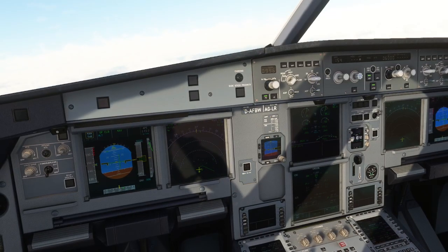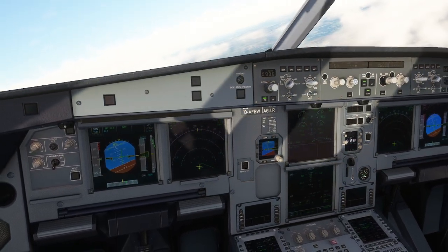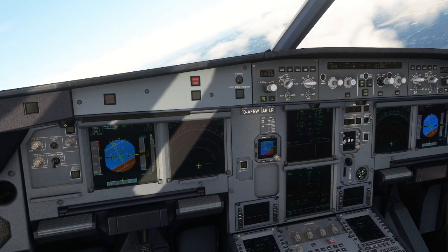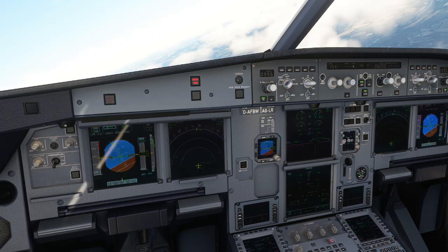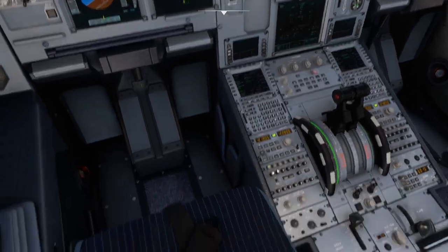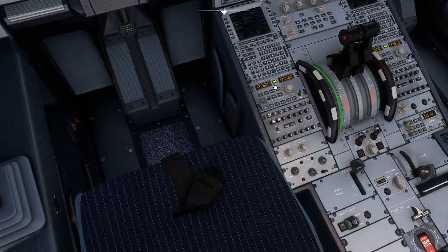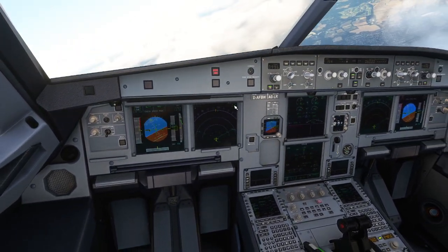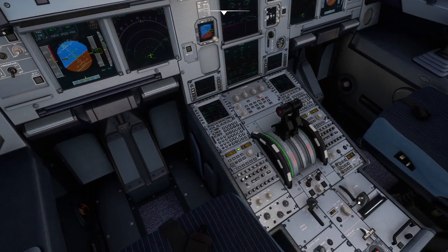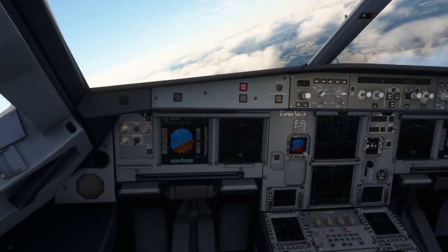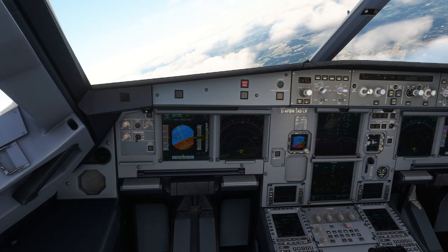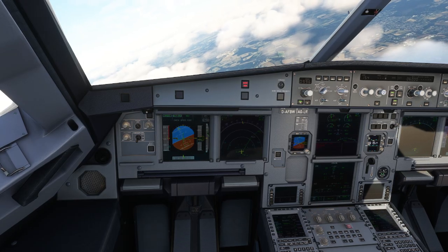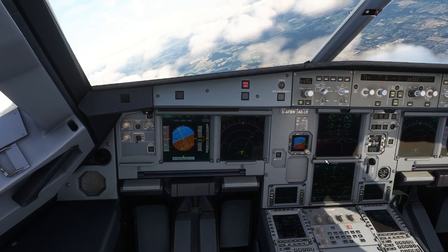Little bit high. So Speedbird 127, surface wind 190 degrees 8 knots, runway 27 left, clear for takeoff. Turn to Unicom. So that is what I'm going to do right now. That means 122.8, the CTAF frequency that is available with me. So I selected 122.8 for Unicom, and I can clean up the flaps for now. That is already done, and my speed is picking up even though I have selected. I think I need to maintain speed, then it will be okay.